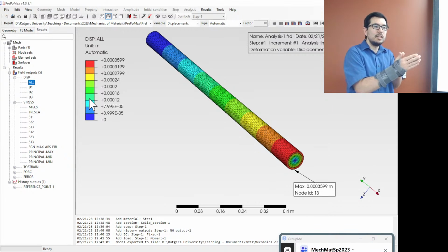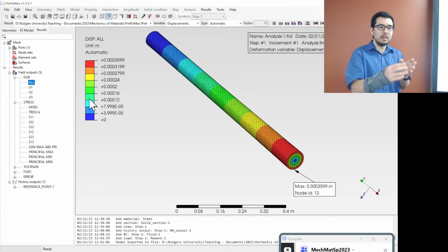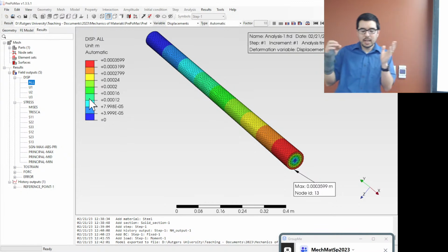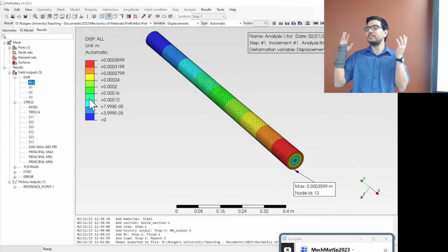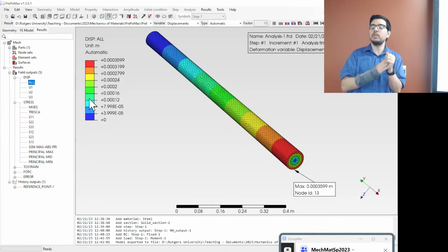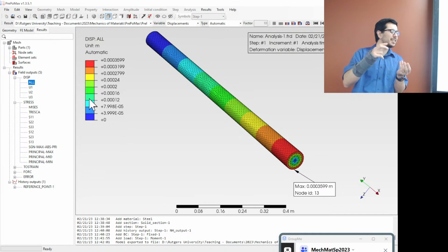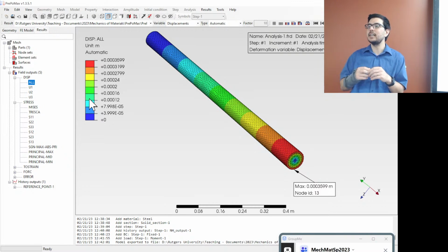So in terms of evaluating whether or not something's going to fail, we want to first make a comparison to the yield strength of the material or the shear strength of the material. Now, we didn't specify what that shear strength might be here. So we could do a design problem and say, you must make it so that the material does not have shear stress greater than, I don't know, 200 megapascals. That's probably a reasonable amount. We already discussed how shear strength is half of yield strength, right? So 400 megapascals is a pretty high yield strength for a material. It's not out of the range of what you can do with steels, but it's pretty high, okay?